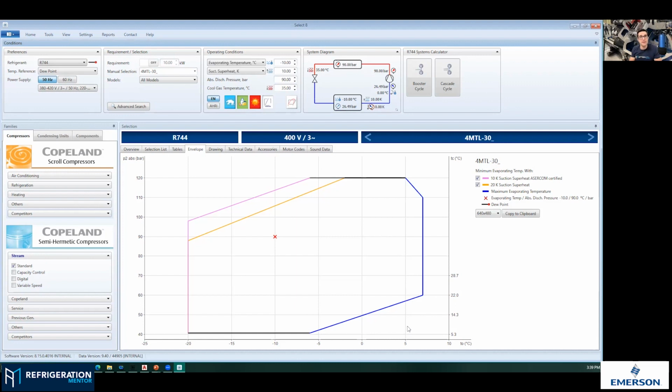So these are some of the things that you want to look for or even think of, because it's not only that the compression ratio is low, but what is causing that? Now you might have to think about a component in the system, a system related issue causing this low compression ratio or pressure ratio.